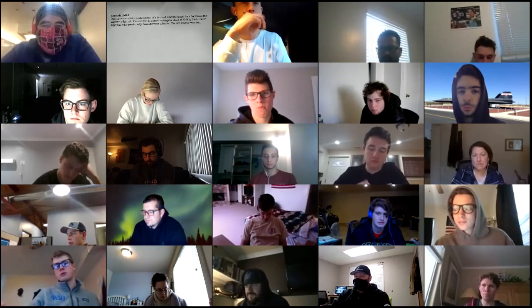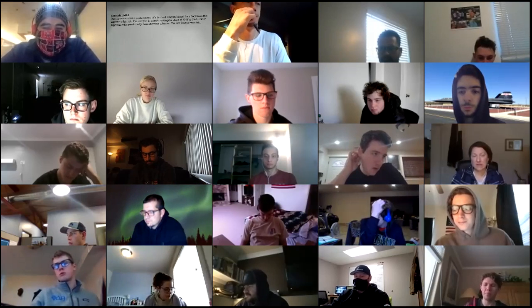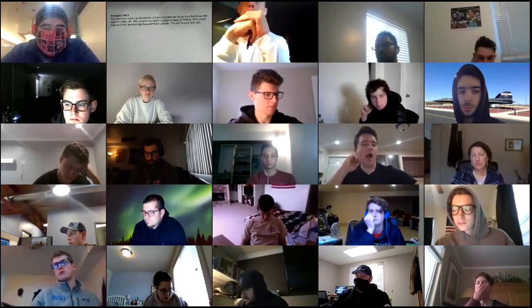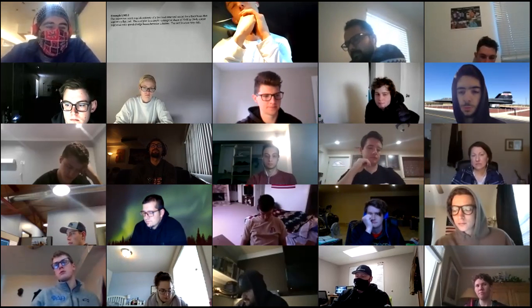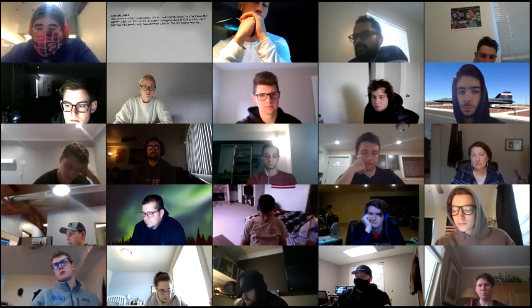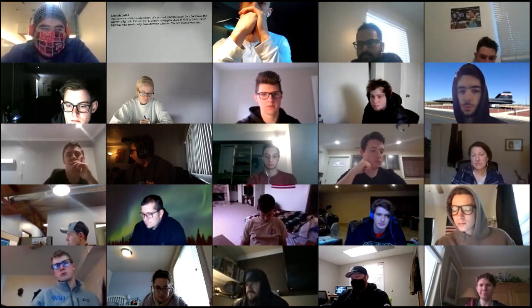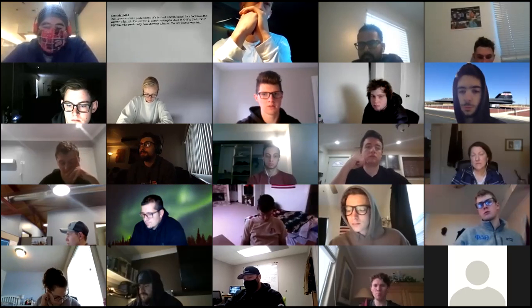That would be an error if you did it on paper too. I would catch that and say, okay, well, that's not quite as good a quality. But if on the other hand, you come along and say, look, the problem statement doesn't say whether this particular level is the ground floor or whether it's above ground, and it matters whether I use 80 PSF or 100 PSF. I've chosen to use 100 PSF because I've made the assumption that it's a ground floor. That's perfectly fine. Make that engineering judgment, but articulate what you're doing and why.